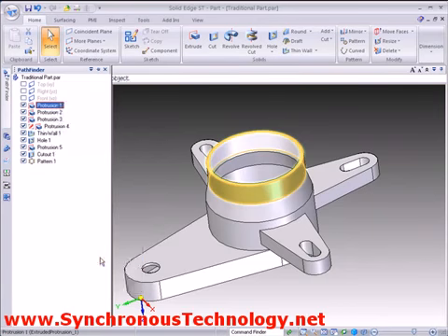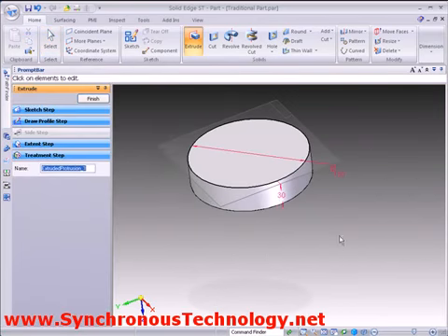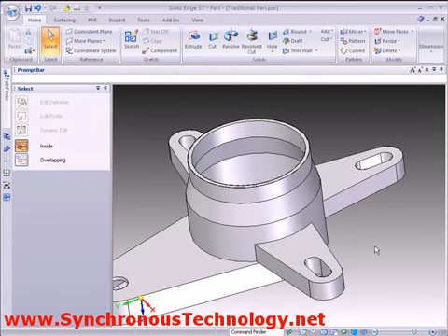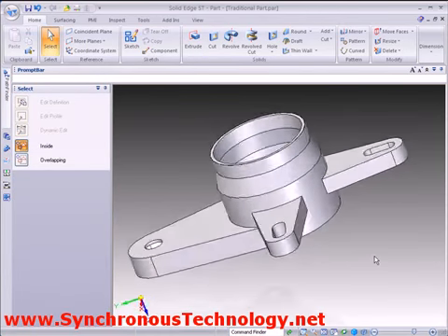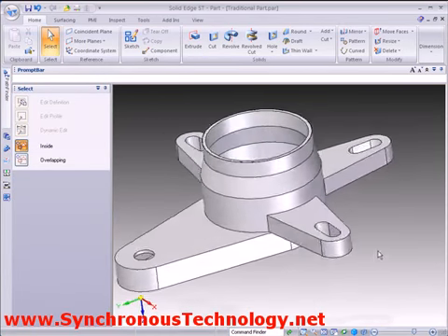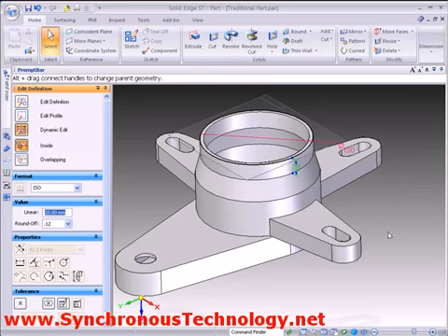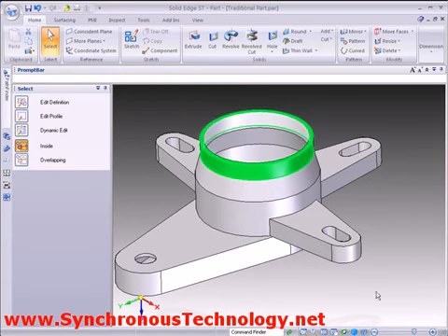Reducing the height of the first extrusion will move the cone shape up as desired. However, it will also reduce the height of the model too, since the other features were built on top of each other, as we can see here. As such, in order to fix things, we need to make another edit to increase the height of the part, as shown here.